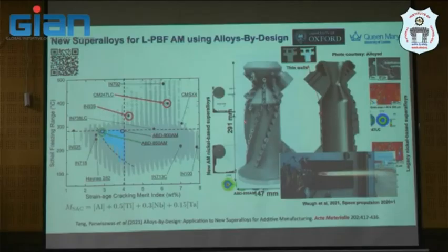The company, the spin-out company from University of Oxford, previously called Oxmet Technology, an alloy company, successfully commercialized this ABD 900 and used it in rocket engines, printing a thin wall structure using a laser powder-based system. It has been tested. I think it's not actually new. It's quite old, 3-4 years ago. It's used, and it came right after we published, at the same time.